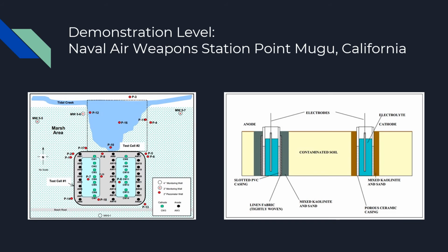Decontamination issues in the site. The site had sodium chloride presence, and this led to production of chlorine gas along with oxygen at the anode wells. This required additional off-gas treatment in the design system. In addition to this, the metal sulfides present in the site led to the production of hydrogen sulfide gas at the cathode wells. A scrubber system was introduced to treat the gas, and it reacted with sodium hydroxide.